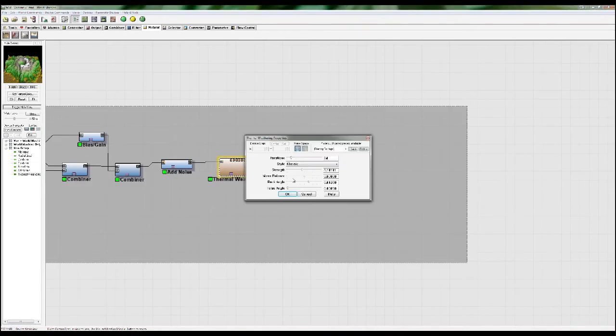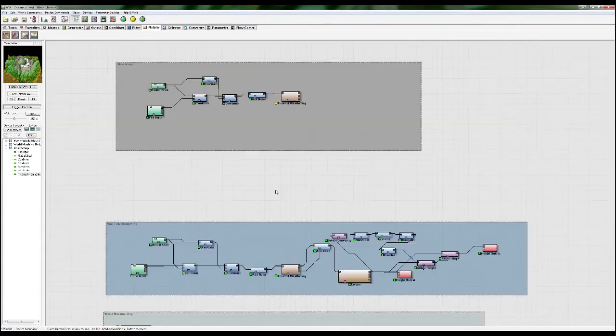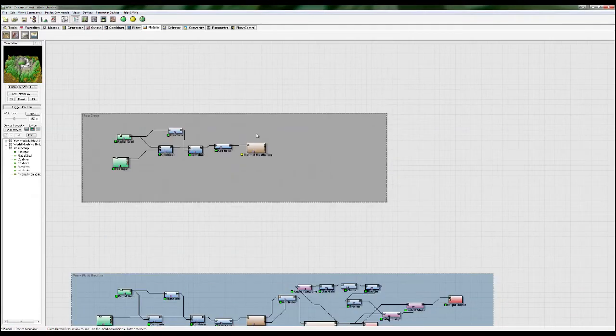And we can tweak these. The rock angle is basically how steep is it before the rock gets taken away. So if this is really flat, then you're going to get smoothing all over the terrain, and if it's really high, you probably don't get much at all. And the talus angle also sort of links into that, where the talus is that cone shape at the base, and the mass balance is how much of it is getting taken away or deposited, and general strength is what it says. So okay, we've done that.